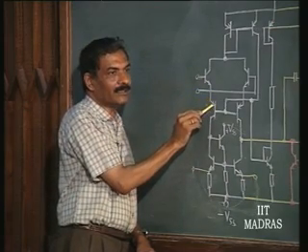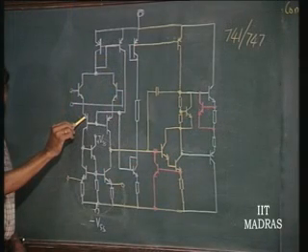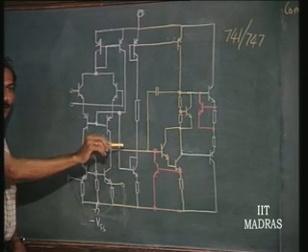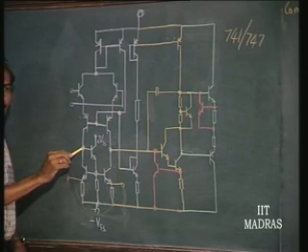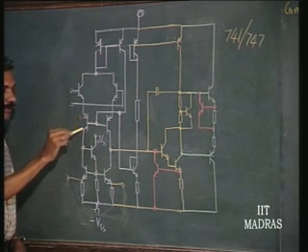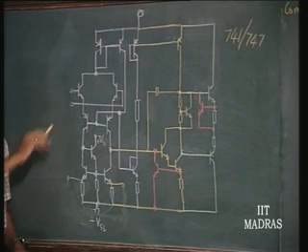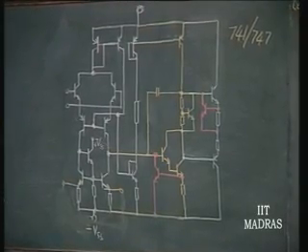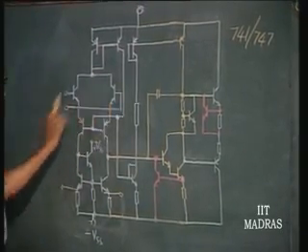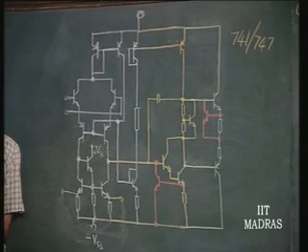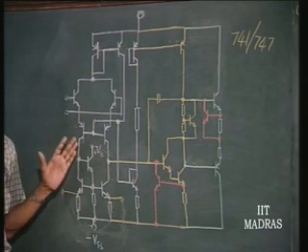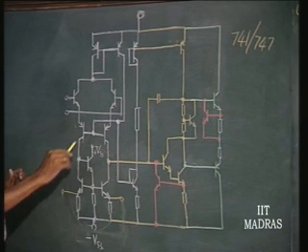This current is going to be the same as the emitter current of this structure, strictly speaking. Base is connected to ground, let us say. Therefore, this is a common base structure for signal. So, you can see that by using this structure, I have got almost a PNP-like looking structure with high beta. This is the trick that has been played in the 741 input stage in order to get PNP-like performance using a combination of NPN and PNP structure. So, that is taken care of.